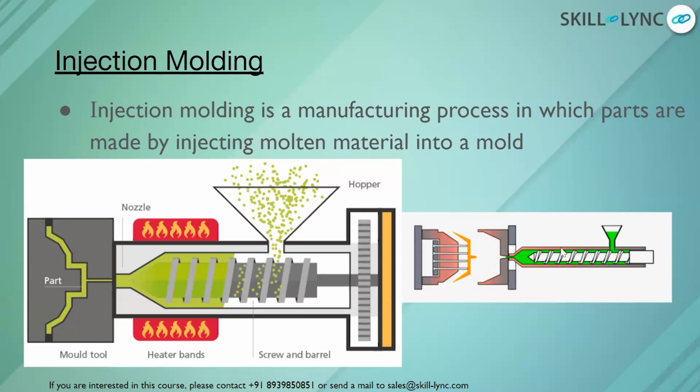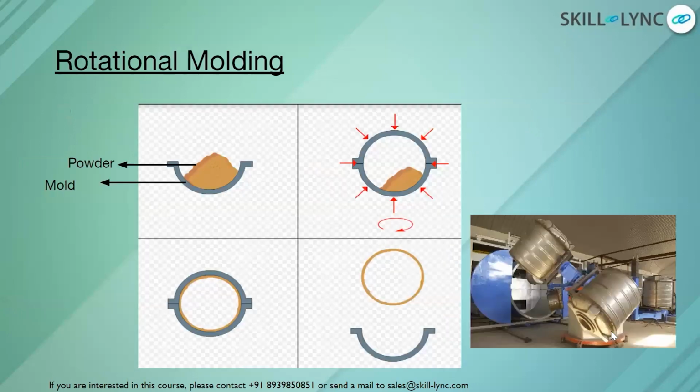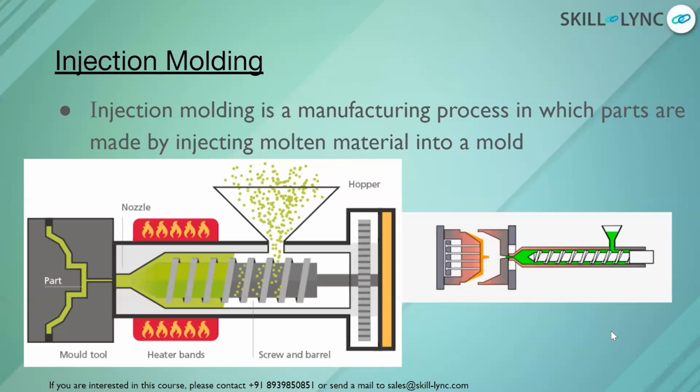In injection molding there are multiple types which you can see. It can be vertical or horizontal, based on the position. That's where you are going to understand how the different core and cavity arrangements work. It's not just simply a core and cavity. We'll also try to understand what the other parts are. Basically, you will have other mechanisms like lifters, side cores, etc., based on the complexity of your part. Accordingly, we are going to work on injection molding.